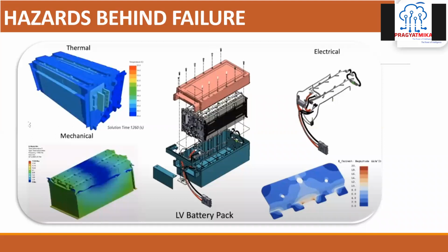Normally for 2-wheeler or 3-wheeler packs, we are very cost sensitive, and we can't apply an active cooling system. So even if you apply a passive cooling system, up to what temperature level can your battery pack go, and for that temperature level, whether you are allowing fast charging or not, that's what you also need to model. All these things are done through modeling. There are the mathematical modelings first, the calculations part, and thereafter, if you have access to modeling software, it is better to model the complete pack.